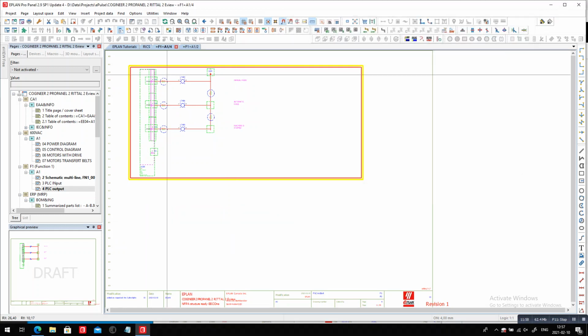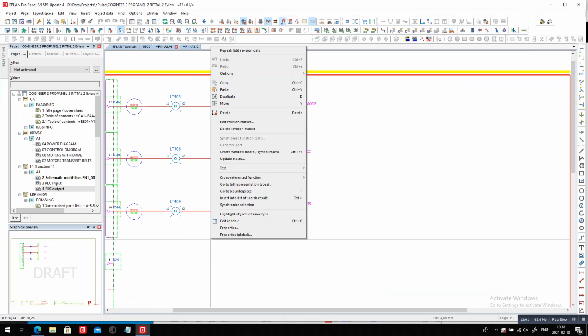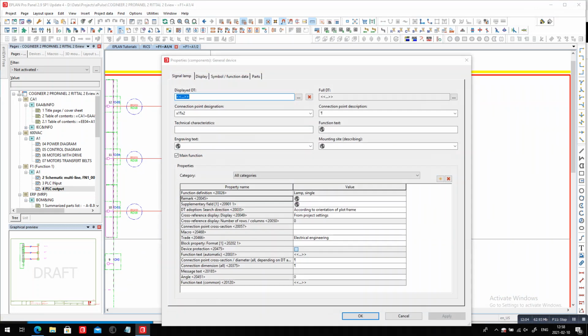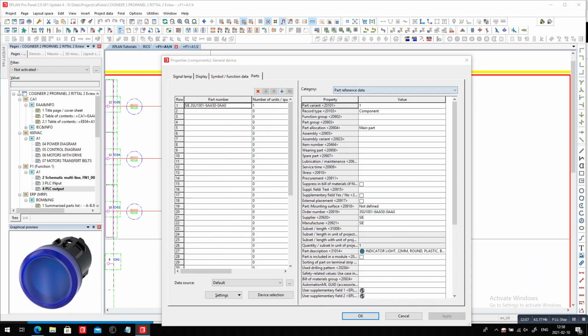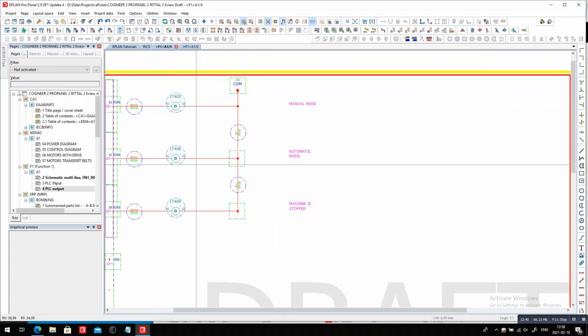lights. Now, what I omitted is to actually specify that these are also new parts. New parts means I will go here in revision in the parts reference data, and for the procurement, because I already did some purchasing, so I have to basically find a way to show everyone that here this has been added. I can put added in R1 in revision 1.0, let's say, if you want, or in revision 1 in R1, and you will see then that this comment could show up on a bill of material. Okay, so this is for these 3.